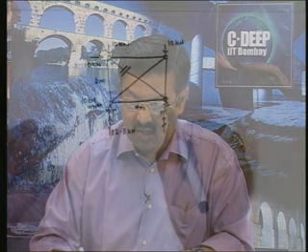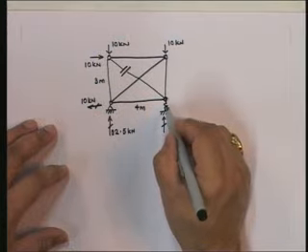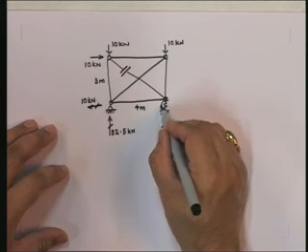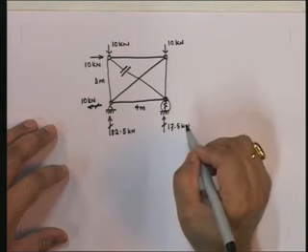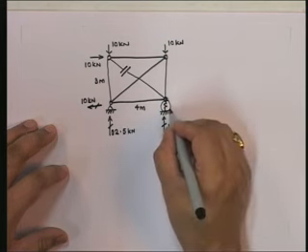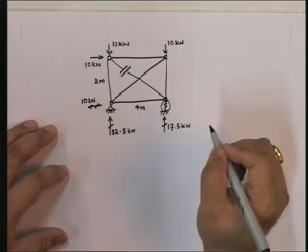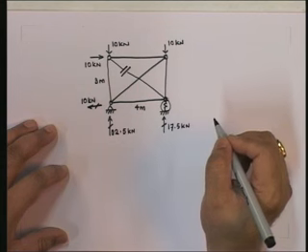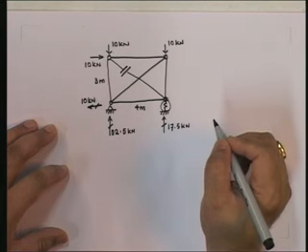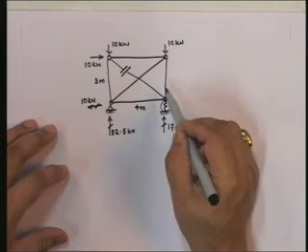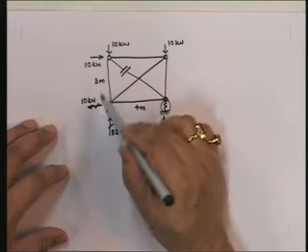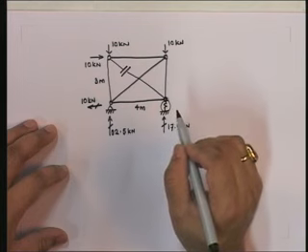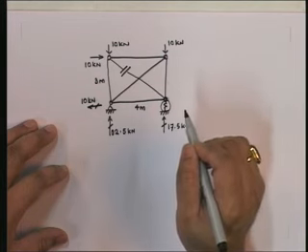However, the most important point here is that whereas in the previous case this deflection was 0 because it was a roller support, in this particular case there is going to be a deflection. But the overall point is that this deflection does not affect the forces in the structure at all. What it may do is affect the displacements in the structure.